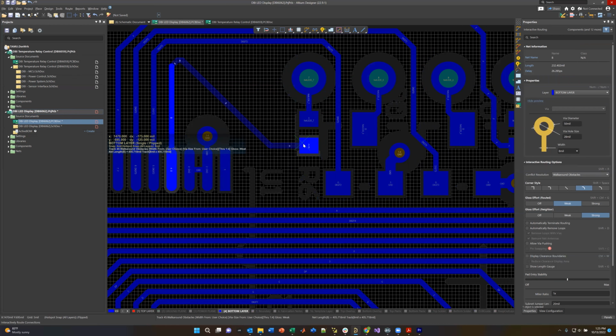Now, if you notice, I also have this overlay. I have these fabrication notes, as it's known. You don't need to do this. I include this. It's a good idea to have a version of this so that people read it so they know what you're building. This is basically board configuration and board statistics. I've been using this very same template for literally 14, 15 years. A lot of times you don't need to include this to get your board made at all.